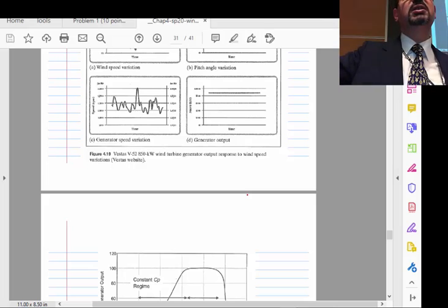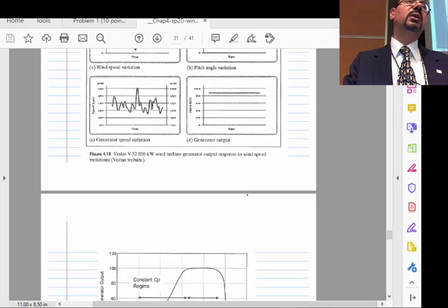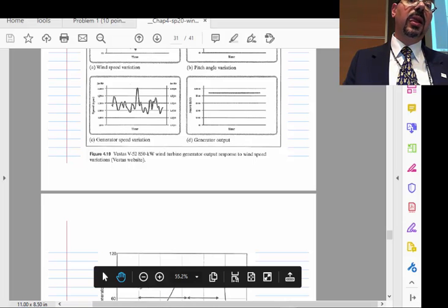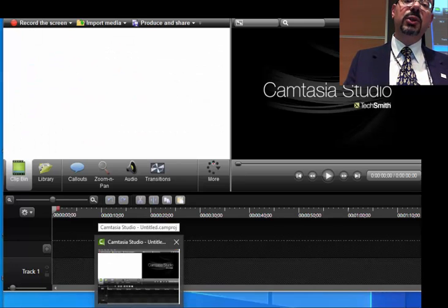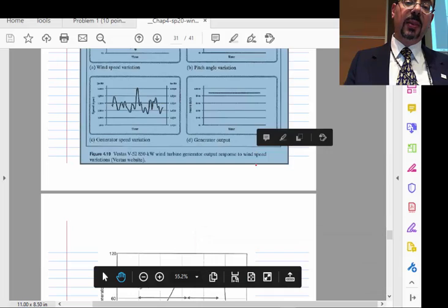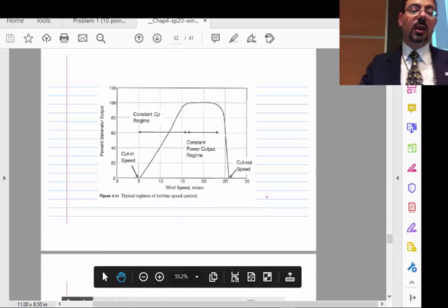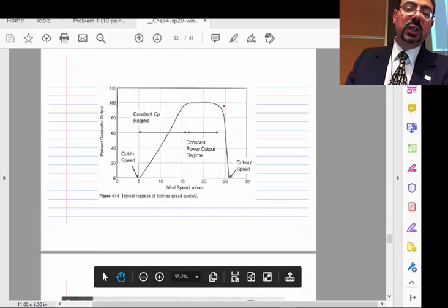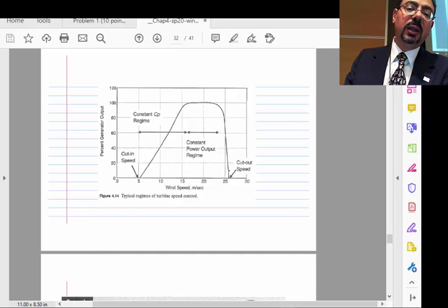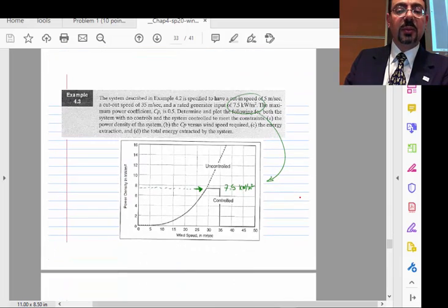So even if the input is higher and higher, you say, no, I don't want it, and you on purpose basically spoil the curve. It's the angle, right? It's the pitch control, right? So one should expect a CP curve to look like this, right? It would rise, stay constant, and then drop to 0.